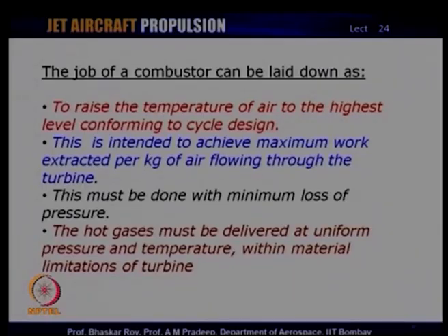Now, we mentioned that combustion chamber works in a gas turbine engine in a flowing fluid. So, it is necessary that it renders this working capability to the turbine in a flowing fluid situation. Now, as I mentioned, this must be done with minimum loss of pressure, because a lot of care has been taken to build up a lot of pressure in the compressor, and one should not lose much of it in the combustion chamber. So, the engineering of the combustion chamber design must ensure that there is minimum loss of pressure, and that is where the engineering comes in.